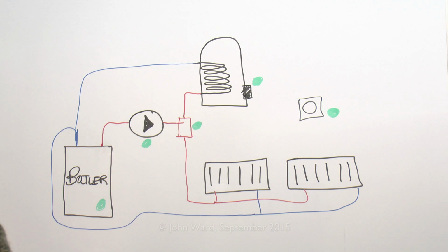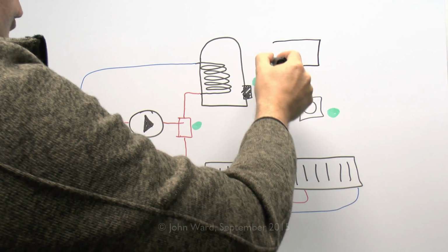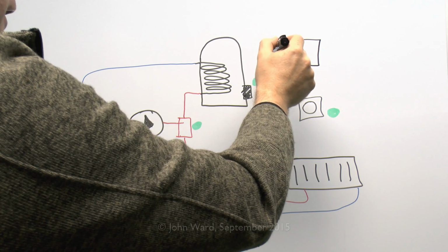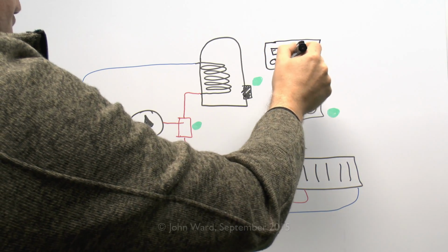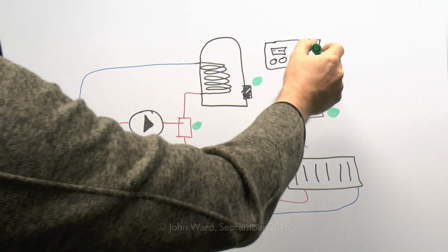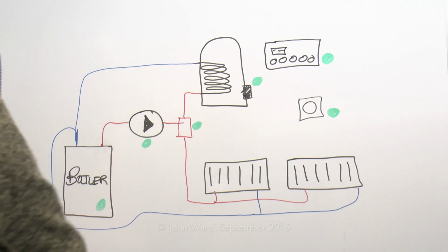And when these are actually attached, there's generally some kind of timer or other control where you can set the time that you want the boiler and the heating and the hot water to switch on and off, and that's generally called a programmer, which is again a wall mounted item, and typically has some sort of digital display on there, and various controls to set the time and duration the boiler will actually operate. And of course that also requires electrical connections and connecting to the other elements of the system.